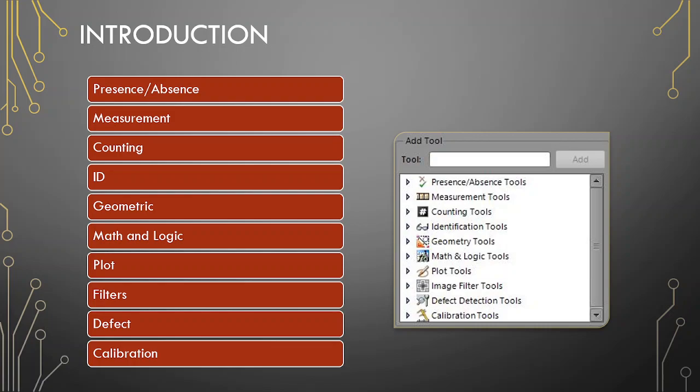Filters, so filters go in a little bit of a broader sense. We have the ability to use filters to determine how we need to maybe change our grayscale or change our coloration. So we could maybe filter out the red light or filter out the blue light. Generally speaking, we use a lot of monochromatic stuff, so we have the ability to filter out and make it more binarized, meaning it's black or white. It's not got any type of shade of gray in it. It's just black or white from the best judgment of the vision sensor itself.